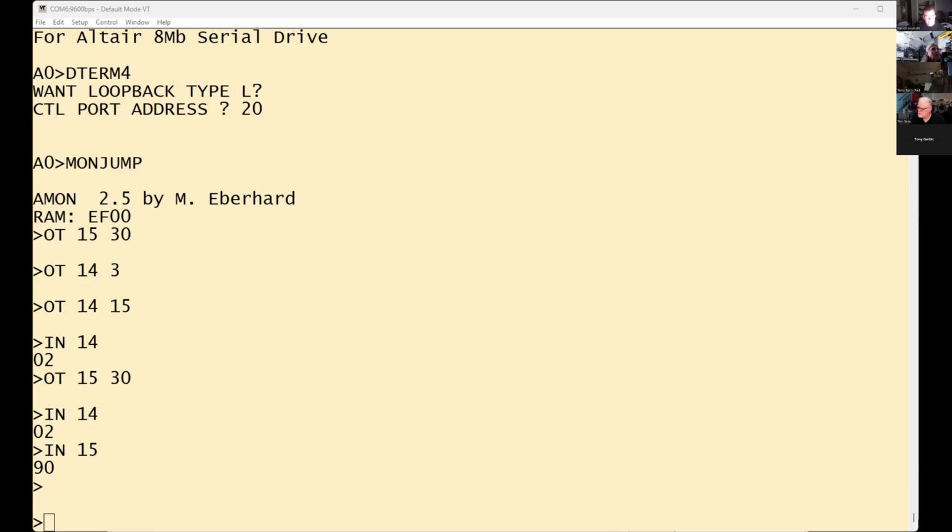So what do I do now? Well, let's see. What baud rate is your Tera Term at? Oh, it's set at 9600. It just needs to be the same as your 2SIO. Okay. Let me take a look at that 2SIO real quick. Because I was flipping back and forth on the baud switch.